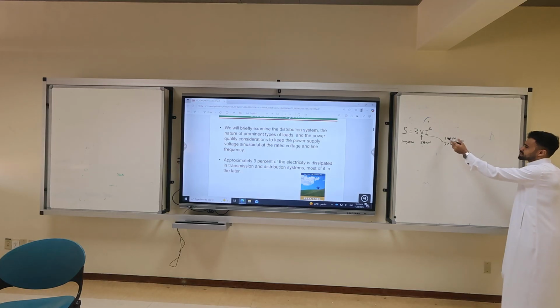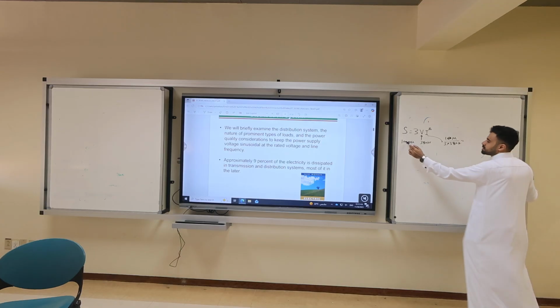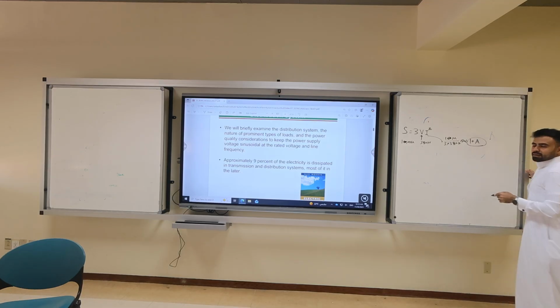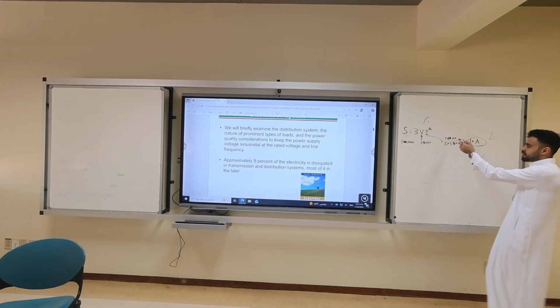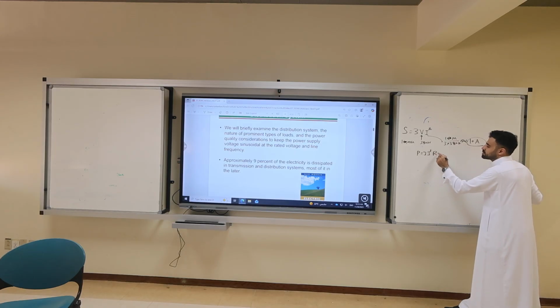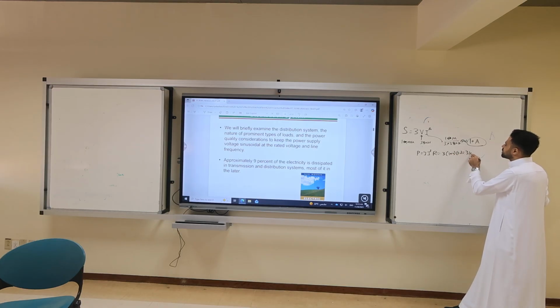Well, let's make it a small system. Let's make it 10 MVA. Let's make it simple. 10 MVA, what's the current? 8.77. So let's say 10 amps, right? 100 MVA is a big system. You need more than one line to transfer the power. So what is the real power loss? 3I squared R. Let's say R is 10 ohm. 3 times 100 times 10. That's roughly 3 kilowatts, right?